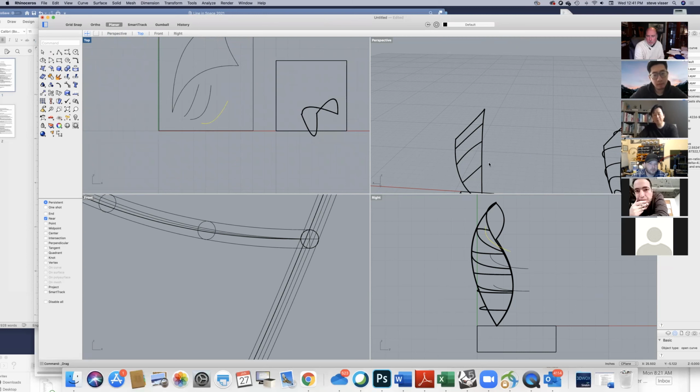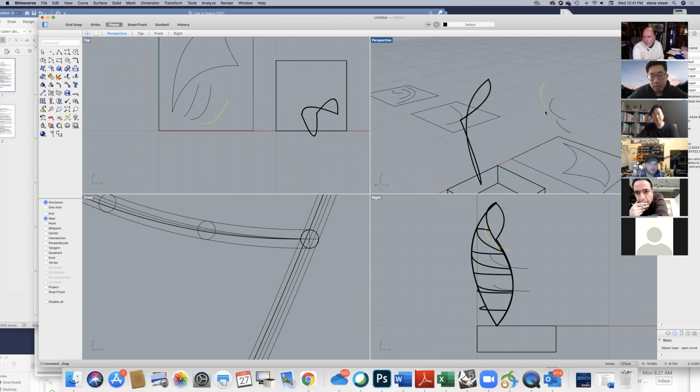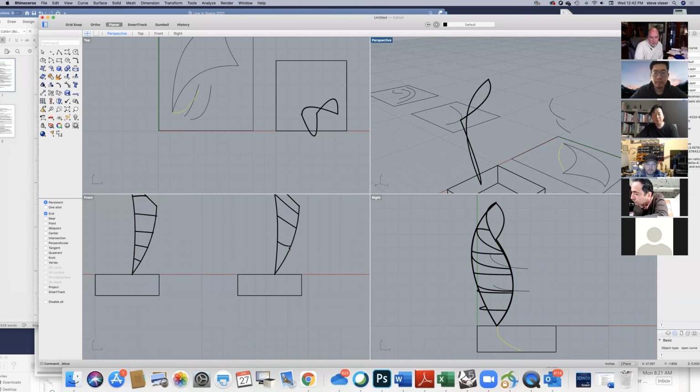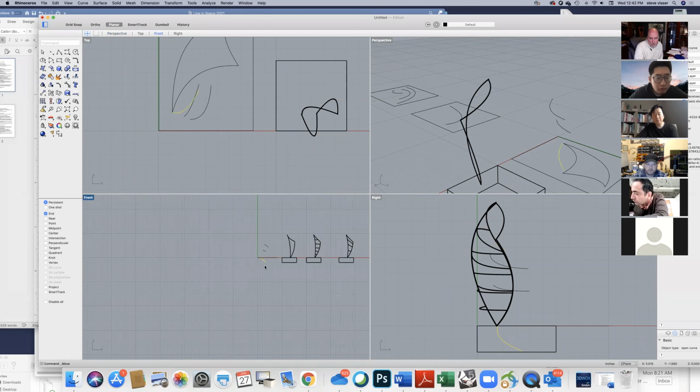However, as I look at them in 3D space, you can see they're floating up in the air. I need to bring them down to the surface. So what I would recommend that you do is move and use endpoint to move them. So I'll take this bottom curve. Oops. Try again. You have to move the selected one. Endpoint down there. And then I can see if I look at them in the other views that they're not laying flat on the page.